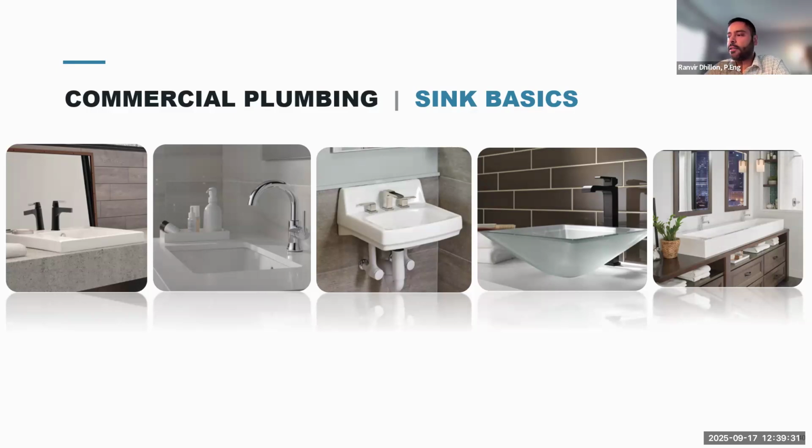It's going to depend on a number of factors. For something like a wall mount or where you don't have anything underneath, your only option might be a mixing valve in the faucet or a recessed box. So that picture that we had of an example of a recessed box, that will be something you can use as well, where you don't want something exposed. Point of use mixing valves are usually for a single faucet, and then for larger banks, it will usually be either the recessed box or a larger mixing valve that can be hidden away under deck.